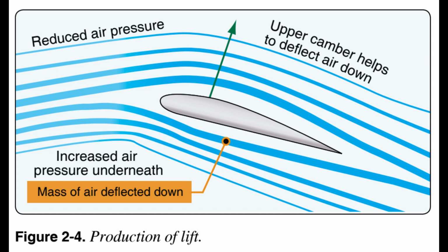At the same time, the flow forced under the object is rapidly slowed or stagnated, causing an area of high pressure. This also causes the flow to accelerate along the upper surface of the object. The two sections of the fluid each leave the trailing edge of the object with a downward component of momentum, producing lift. Figure 2.4.